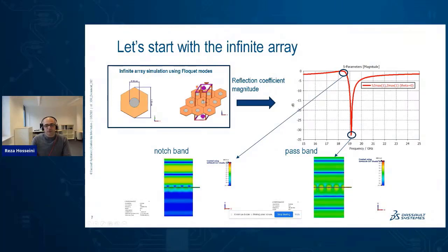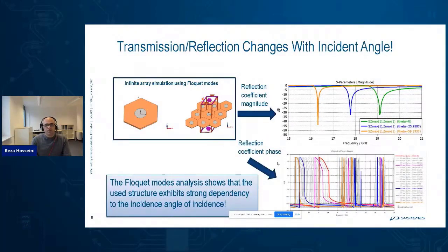So these are the fundamental frequencies pointed out here, because we're going to address these frequencies later. So this concept of passband and notchband is important here. The other important factor is that the transmission and reflection also change with incident angle. The previous slide's field animation was for the normal incident angle.